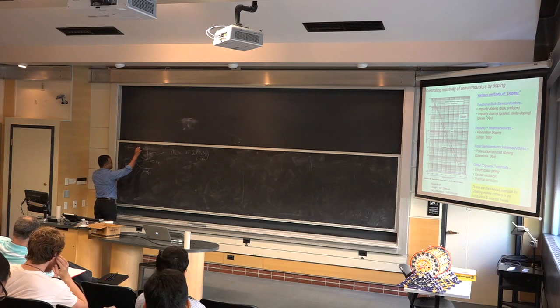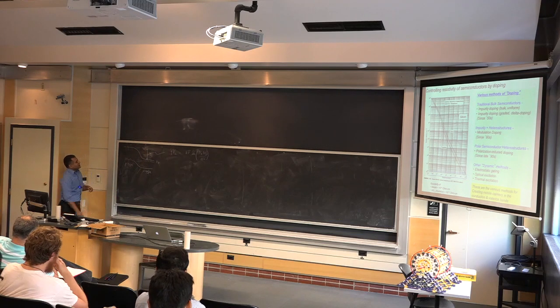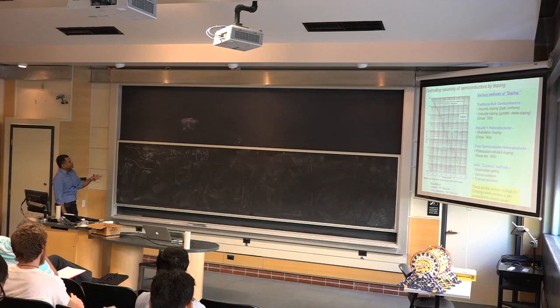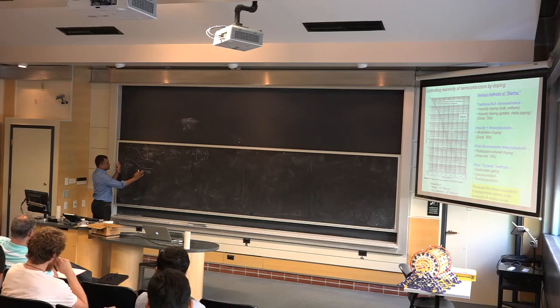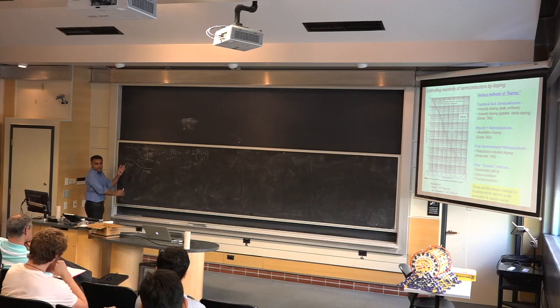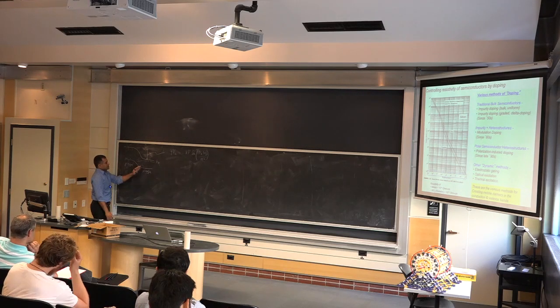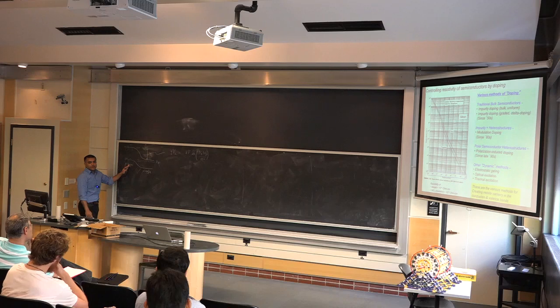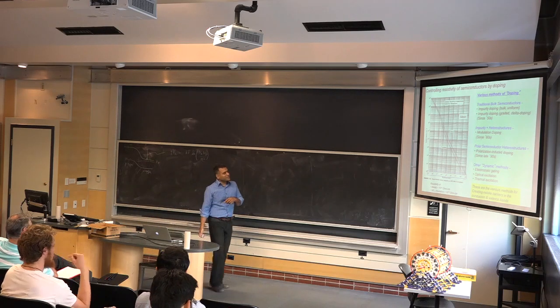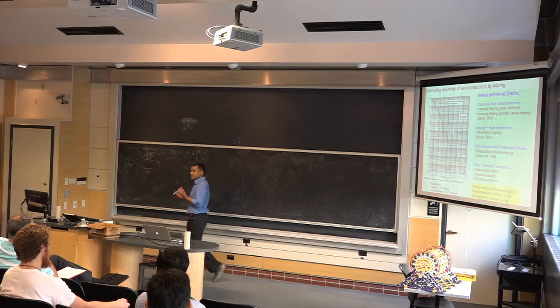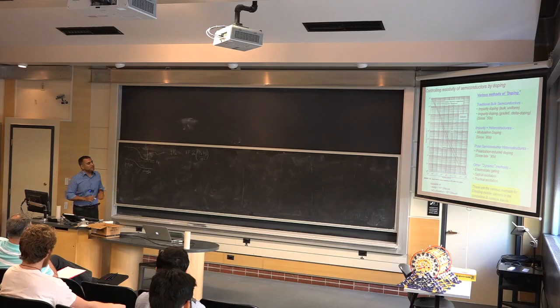and spend time going into the details of the functional form of this, and look at various sorts of junctions. This is a p-n junction. We're going to look at what if I had a junction where the doping densities are different, so a p-p junction. What if I had a semiconductor-metal junction? What if I had two semiconductors with different band gaps? Those are all different junctions, and all of them help us in making devices of different kinds. They are really the building blocks of many of the device technologies.